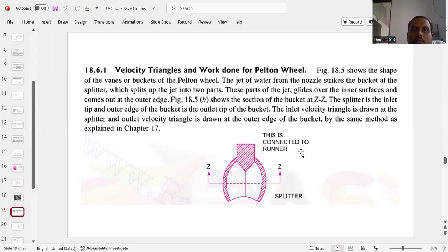At the same time, the vane rotates with the blade velocity, which is called u, or tangential velocity. The difference between this tangential velocity and the absolute velocity we call the relative velocity. It is present for both the inlet velocity triangle and the outlet velocity triangle.